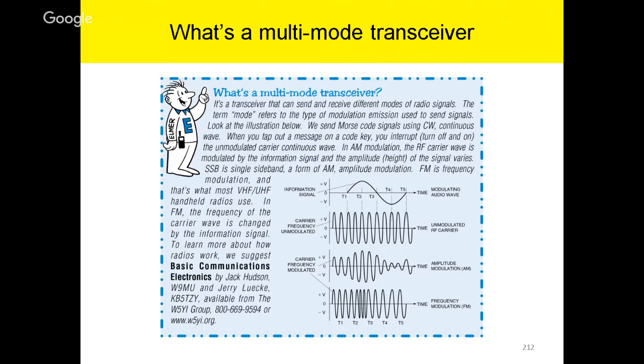It's an unmodulated frequency. So if you just keyed up your microphone and looked at your oscilloscope or some other instrument that can pick that up, you see that frequency there. That's just a frequency, and it's unmodulated. It's a dead carrier, and there's no intelligible information on that.